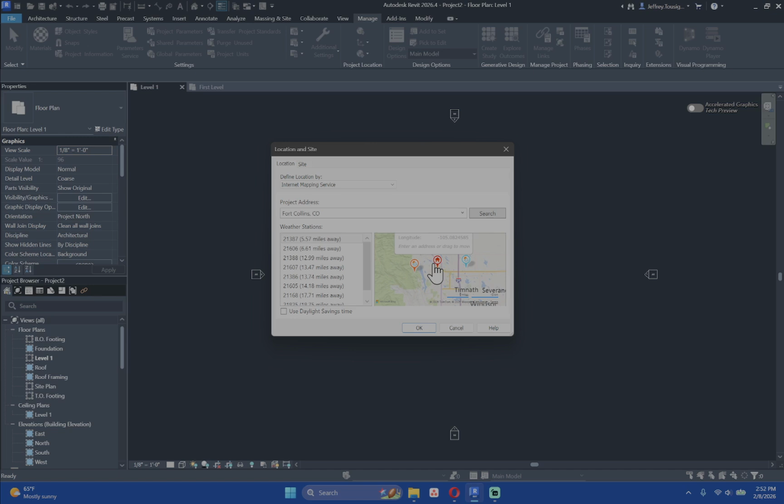You will want to get quite exact with it because on the lower end level of locating this, you will always want to generally locate every project you have at least to the city, because when you are doing photometric studies and solar studies and inputting the information or linking this into Forma, Forma and the photometrics like to see these items at the correct locations, because then you will see the sun and other weather environmental effects actually replicate what is going on in that area.